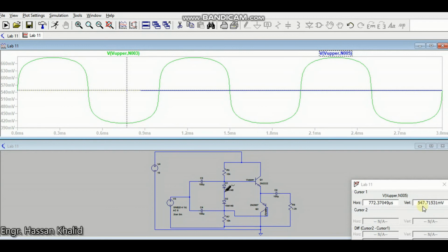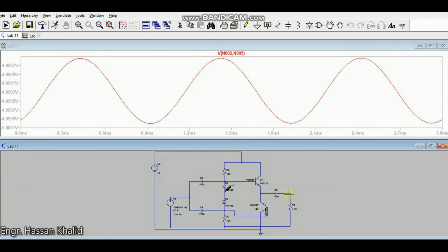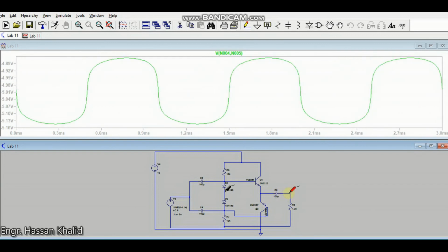So here what you should do is try to find diodes that have exactly the same characteristics as the base to emitter junction. If you are able to do that, only in that case the output will be exactly the same as the input. Okay, this is today's tutorial regarding the solution and how you can easily cover up the crossover distortion.